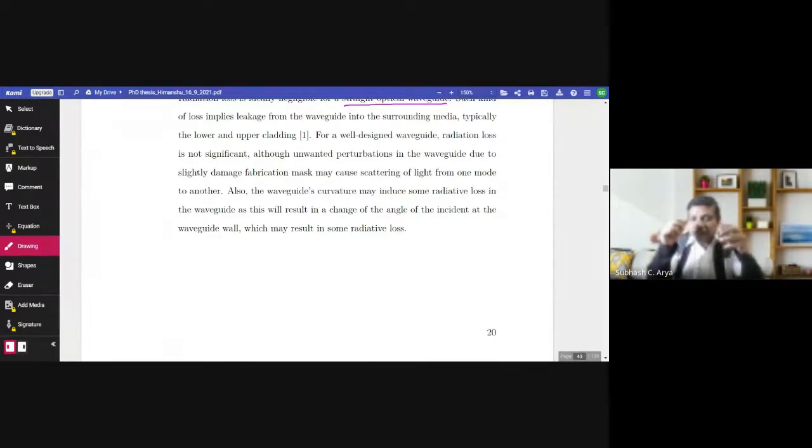How does scattering occur? When a particular light is coming having, say, lambda as the wavelength, suppose 1.55 micrometer, that is some dimension, and the light which is passing through that medium also meets some smallest particles in that medium, and if the particle size corresponds to the wavelength of that light, what will happen? They will scatter.